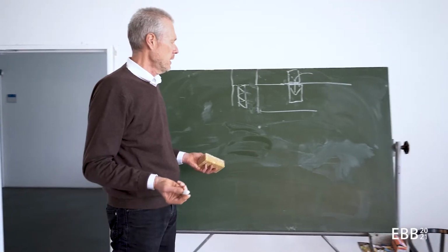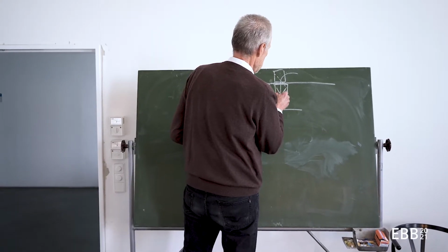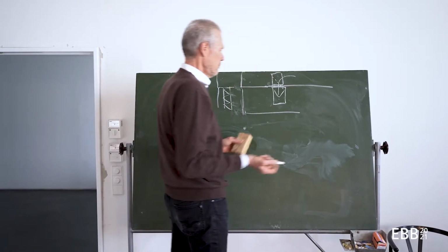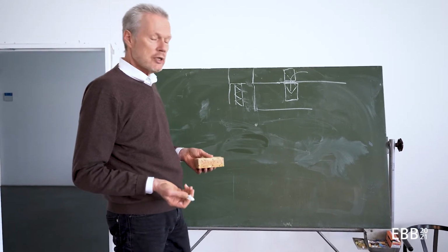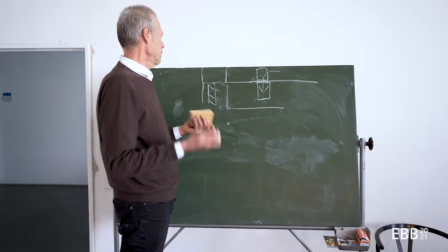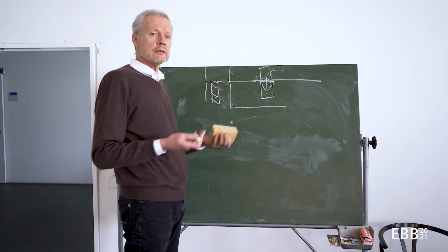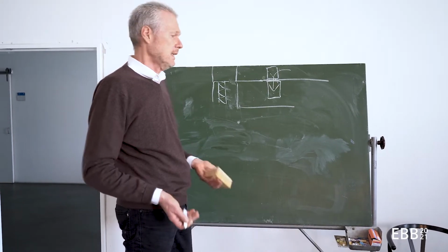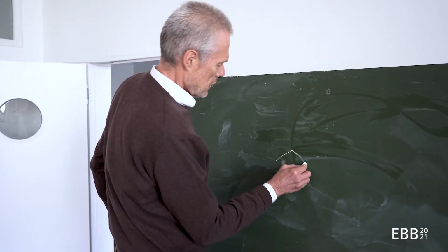If this is the case, I will have to create a connection between secondary and primary construction, and for this traditionally I often use metal connectors. So this often helps to create a connection, although it's not always what I want aesthetically. So the one solution would be a joist hanger.